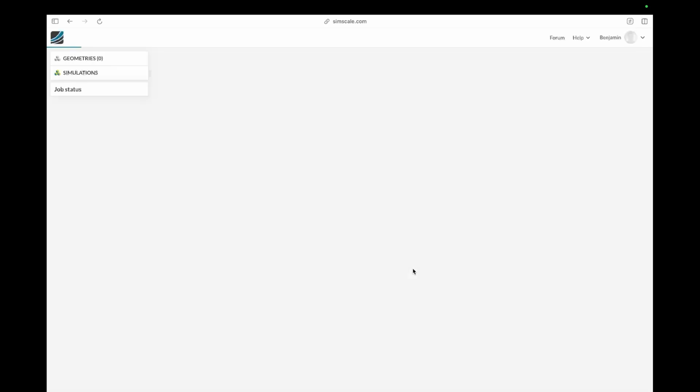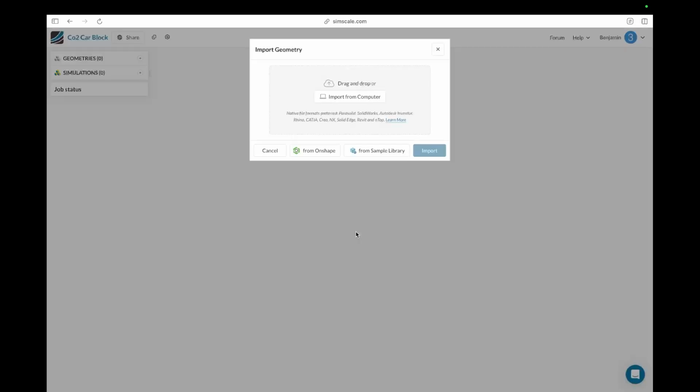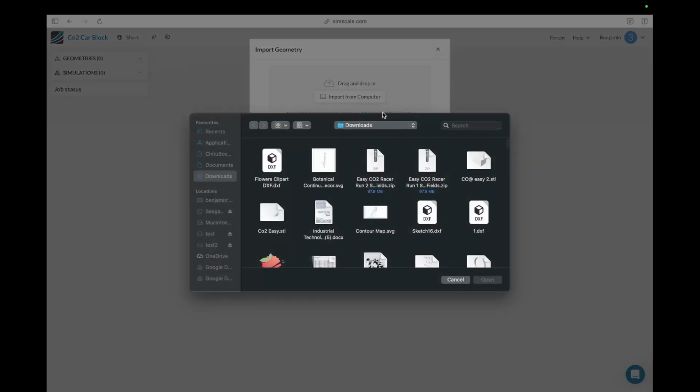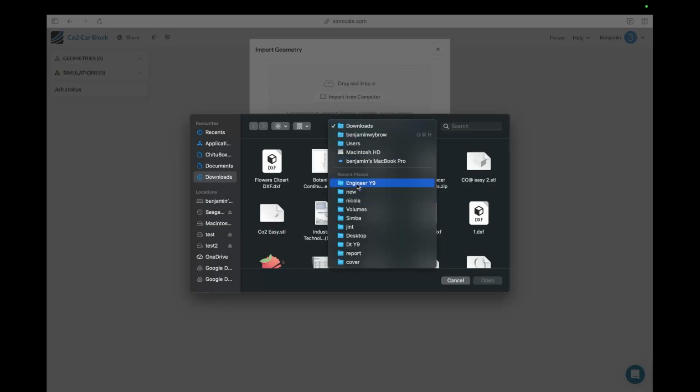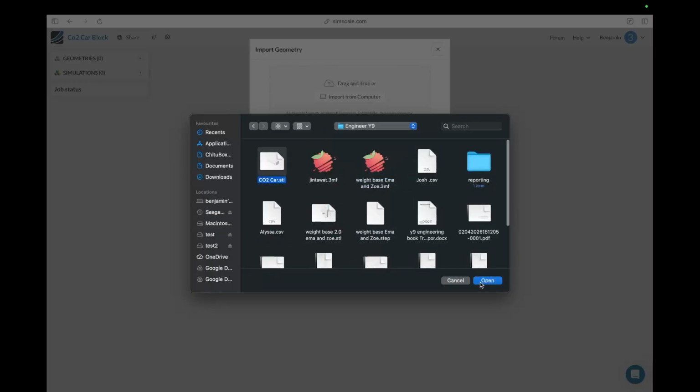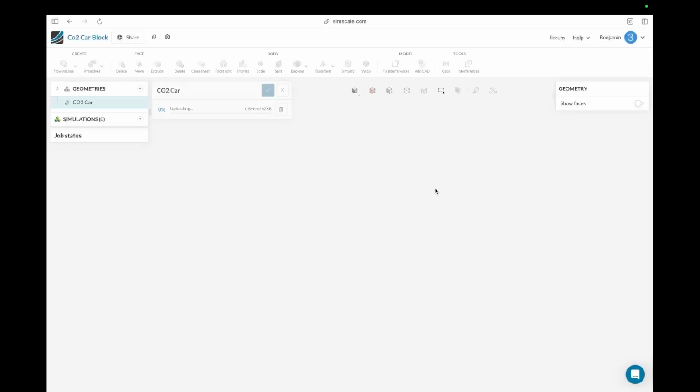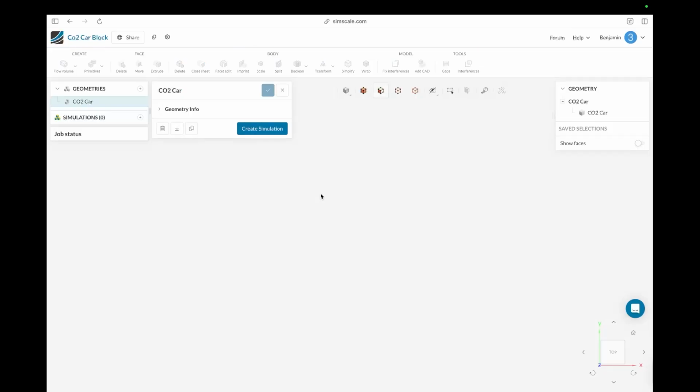I don't think anyone's going to come find your design and steal it, so I wouldn't worry too much about that. It's going to load up this file and it's going to ask you to import the file. You can import it from other CAD programs, but from Fusion we can't, unfortunately. So we're going to import and we're going to find where we just saved our file and then open and then import. It's going to take a little bit to import. All right, happens pretty quickly. And it works it all out. And you can get your block here, like so.